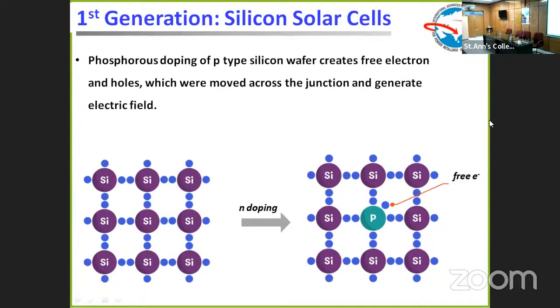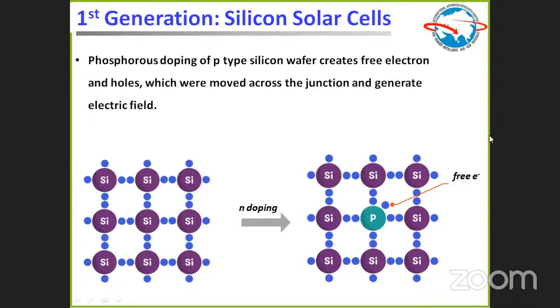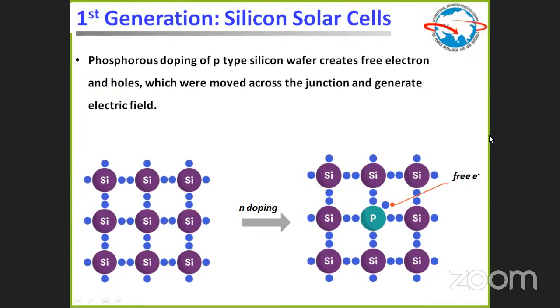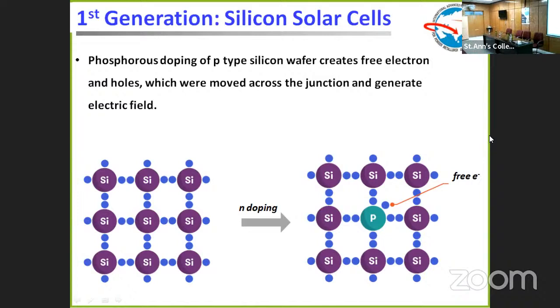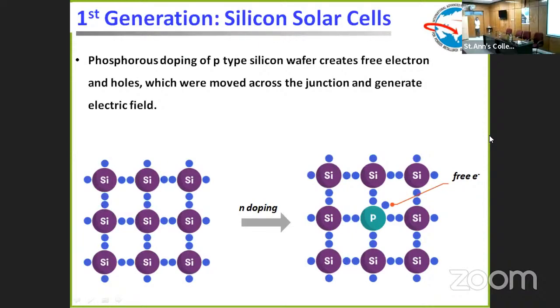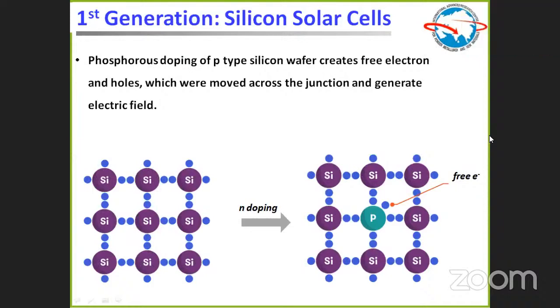We all know that silicon comes from SiO2 through different chemical approaches, but you can take any silicon, it could be P-type silicon or N-type silicon, and then you create a PN junction by doping. So we are not taking two different materials, P and N-type, just take any one, and by introducing doping, the top layer is converted to the opposite type. So you will get a PN junction. It's like a homojunction. Once you have a PN junction,